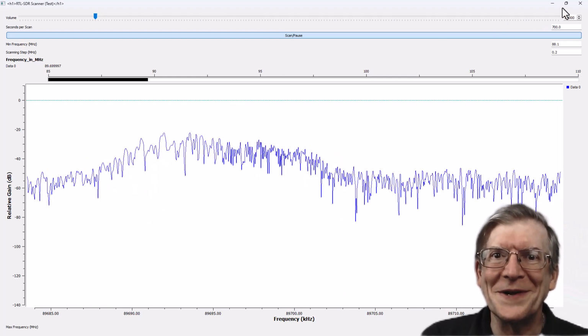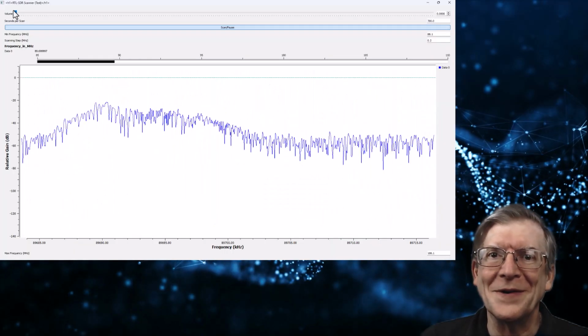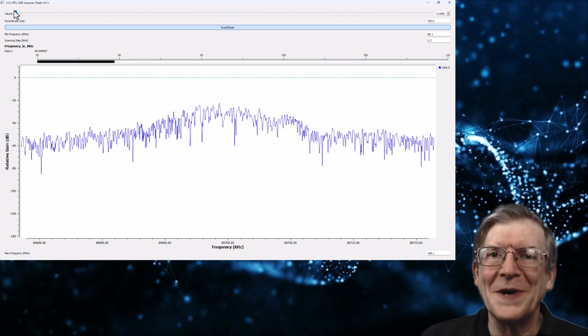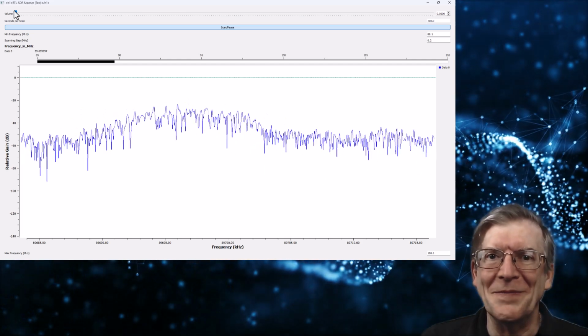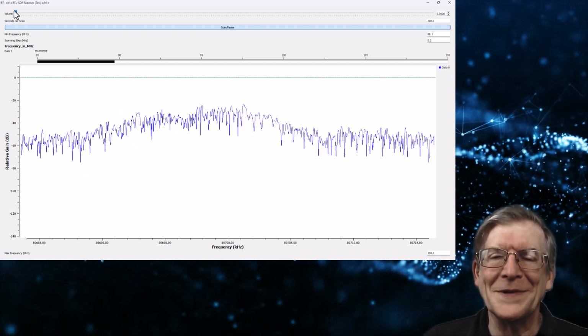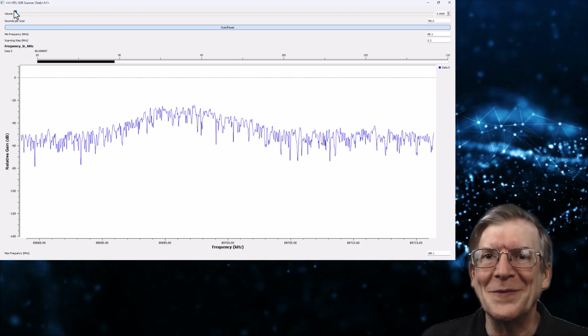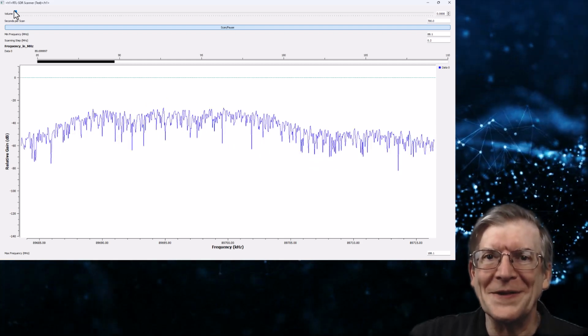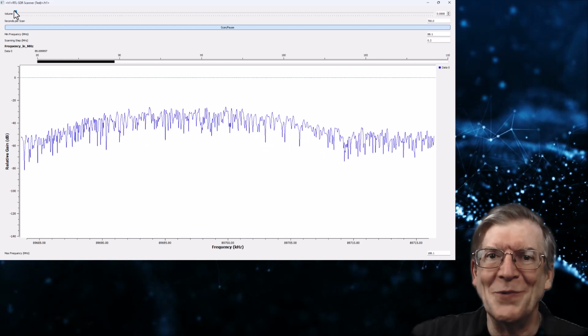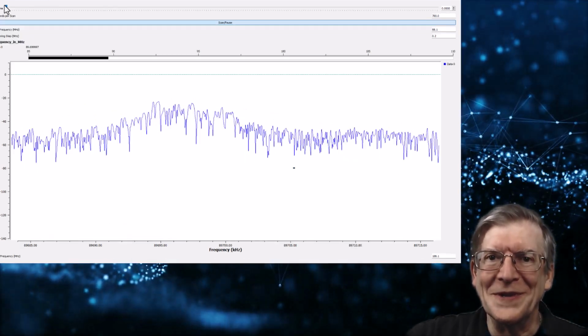So that's a basic FM broadcast band scanner built using GNU Radio and an RTL-SDR with no real Python coding, just some minimal math expressions, and just as an example of what can be done in that way. However, you can do much more if you use Python code in GNU Radio, and you'll see one example of that in the Marine Band scanner linked to in the description.